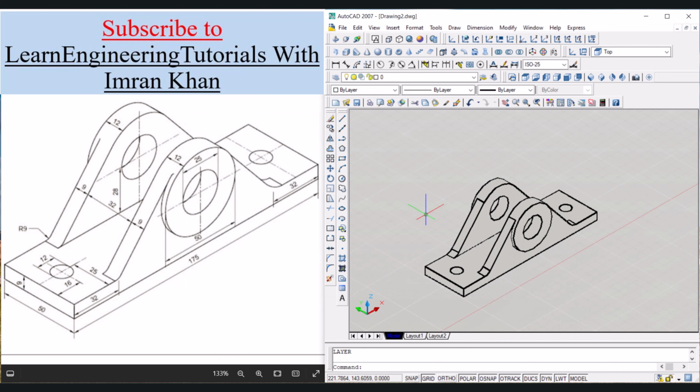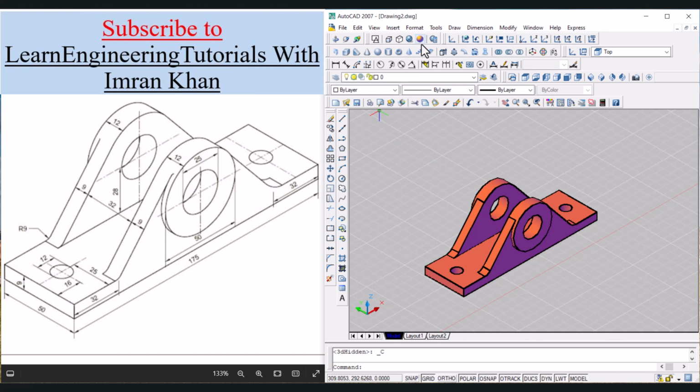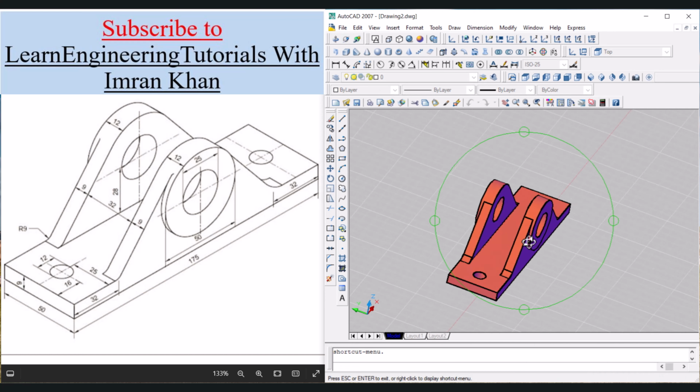So now this is the southwest isometric view. Now if you want to give color to this object, we can just click over here and choose the color by the first box of the property menu, and here we can select red or whatever we want to. So in order to visualize, we have to click on this conceptual visual style, and now the color has been given to this object. Click on orbit, and now we can visualize how this object will look like.